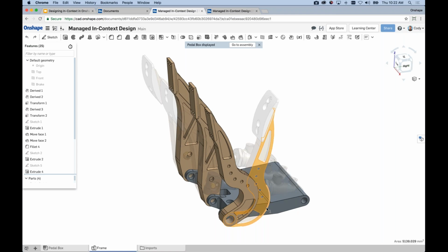Now, that also means it's important to emphasize you'll want to get the assembly into the correct position before you edit in context. You'll want to move parts around. You'll want to hide parts. If parts have no relevance to the context or the features that you're creating, you can hide them before creating the context and they won't show up. So you'll want to take some thought into where my parts are at. Are they hidden or are they shown? But again, it just grabs it, brings it into the Part Studio, and you design around it. Now, I haven't actually created a context yet. I haven't really established a relationship to that ghosted assembly yet.